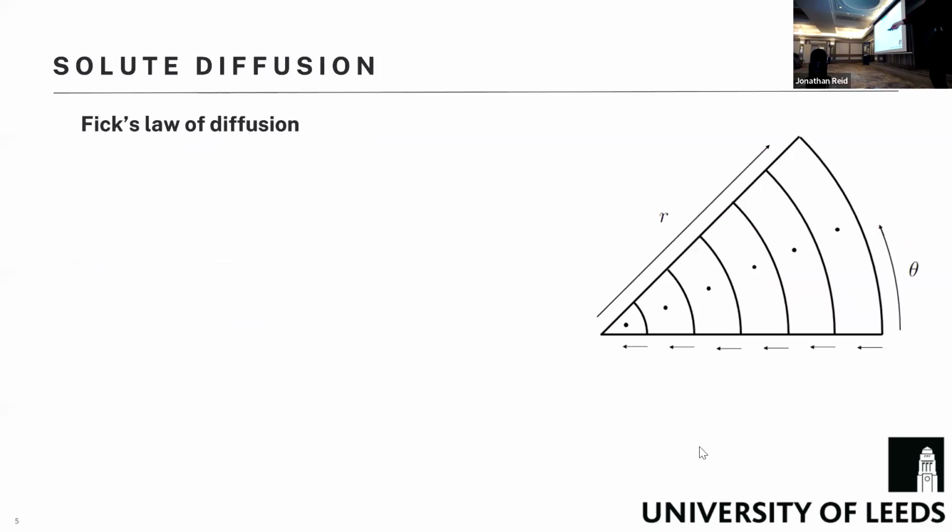Right, so as was mentioned by Barney just before, as the droplet evaporates, it therefore shrinks, and the solute sodium chloride doesn't evaporate, so it starts to get an enrichment of the solute at the surface of the droplet, which then diffuses toward the center. So in order to solve this numerically, I've been dividing the internal domain of the droplet into a few different control volumes that we can call cells.